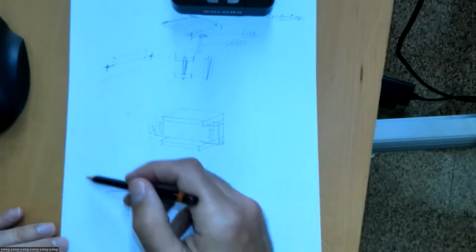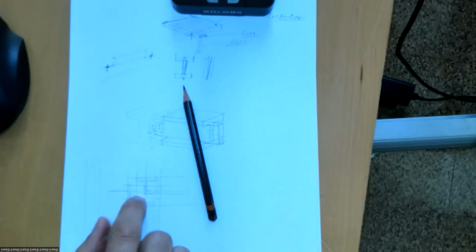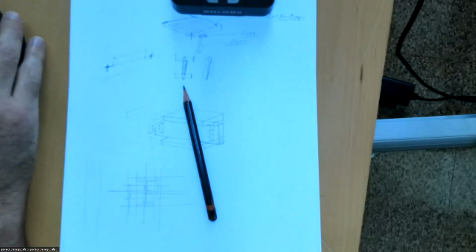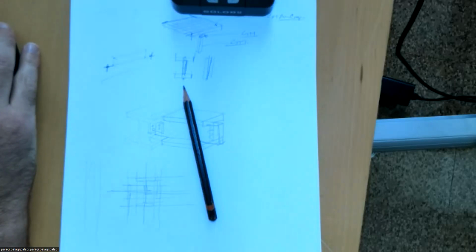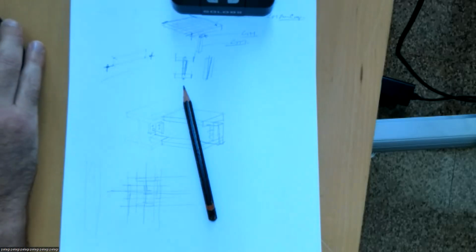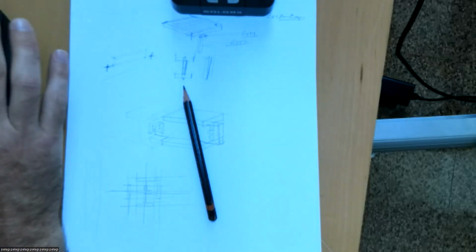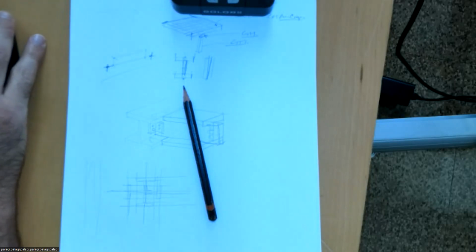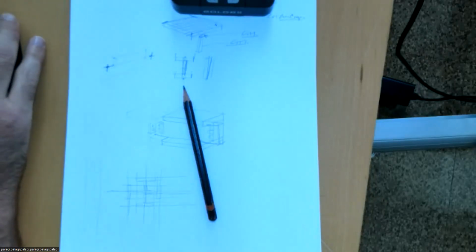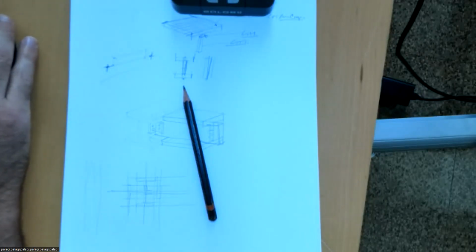On this version, I'm going to do the column straight. It does taper. I'm not going to get into that one because I just want to show how to control these things more than the tapering. Okay, so the first thing I want to do is go into File, New, Family, hit G, bottom. What's weird is that you get different commands. It opens up all the windows, reference, front view, get rid of everything except for when you're on stuff. So we're going to go RE and start to just draw this out.